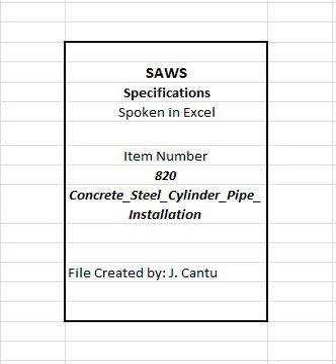15. Pipe manufacturer's certification that PCCP cylinder assembly has been hydrostatically tested at factory for 2 minutes minimum in accordance with AWWA C301 or AWWA C303. 16. Submit the following for non-shrink grout for special applications. A. Manufacturer's technical literature including specifications for mixing, placing, and curing grout. B. Results of tests performed by certified independent testing laboratory showing conformance to ASTM C1107, non-shrink grout.